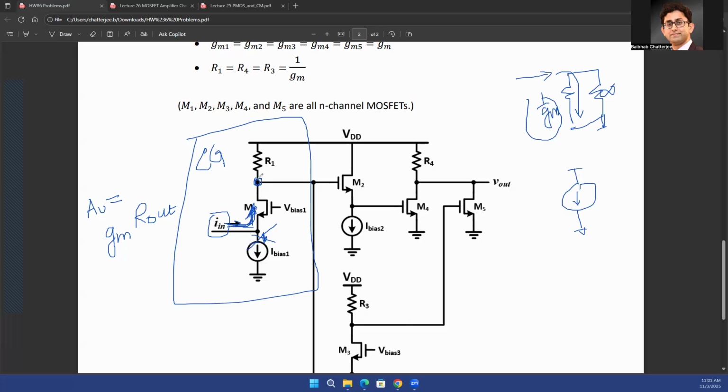and then whatever is the output resistance at the drain node, the current will be multiplied with the resistance and give you the voltage. That's Ohm's law. Current gets multiplied with the resistance, gives you voltage. So all the current goes up, all the current is at the drain node. Whatever resistance you have at the drain node, multiply that with the current, and you'll get the voltage.